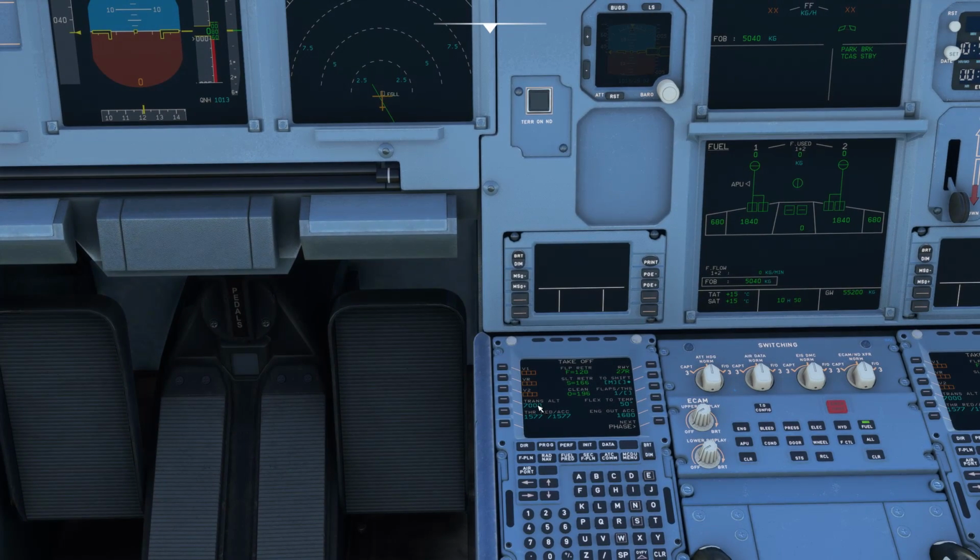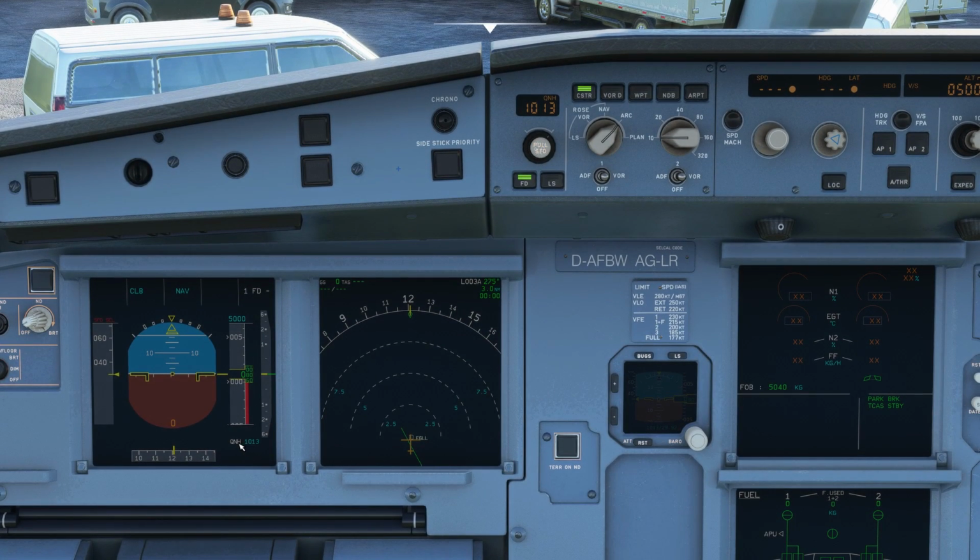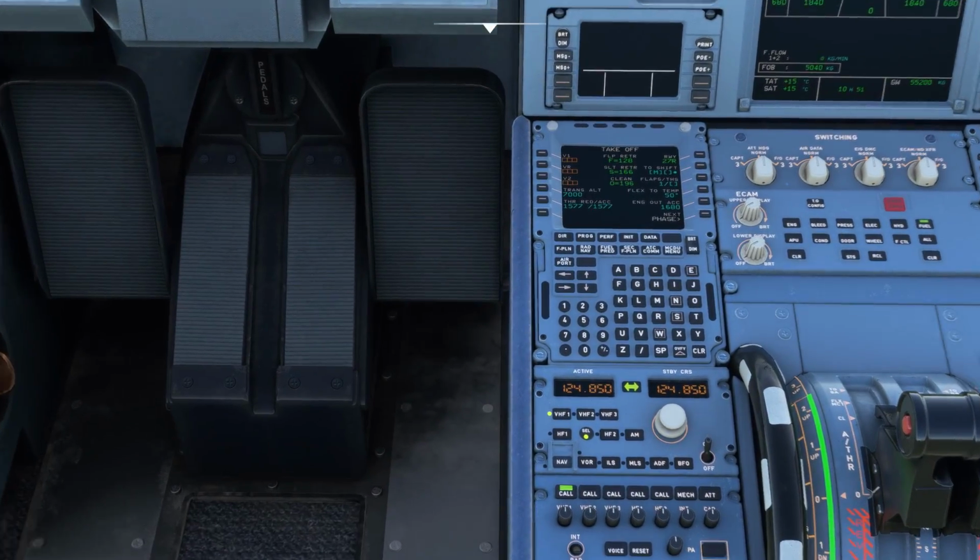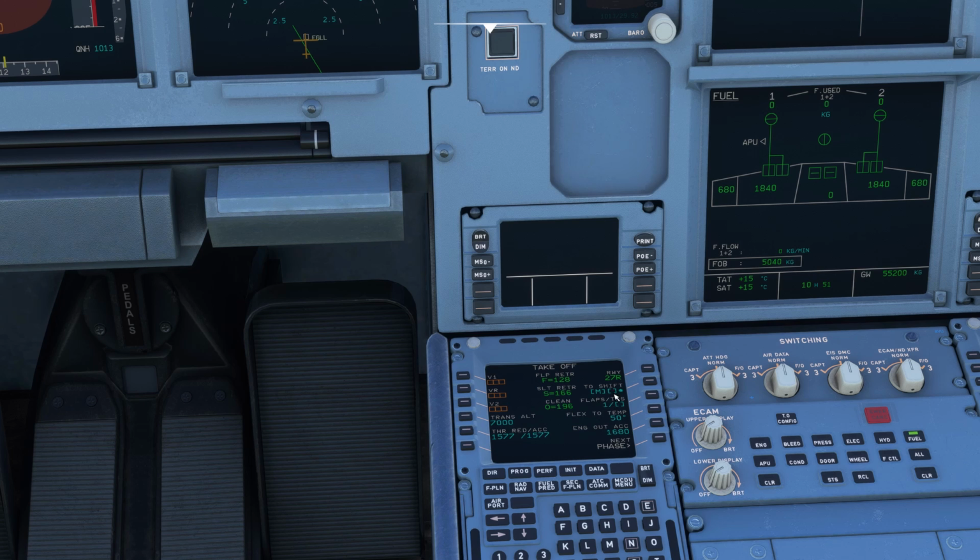All that means is when you hit that altitude, on here where it says QNH, it will start flashing STD, which means to set this to standard pressure, and all you do is push down for that. But you can change the altimeter there as it is, and that changes the pressure setting, and you can see what that's doing is changing the altitude. So 1013 is the standard. We'll keep it as it is, and then as we get to a certain altitude we'll press standard to set it to standard pressure. So we've got all the information we need in there.